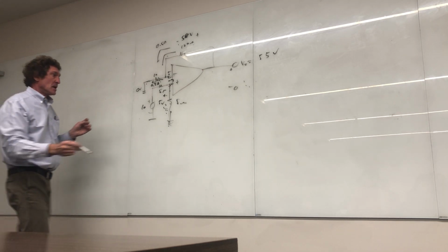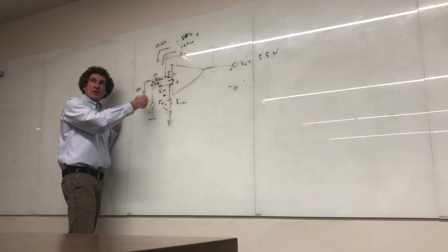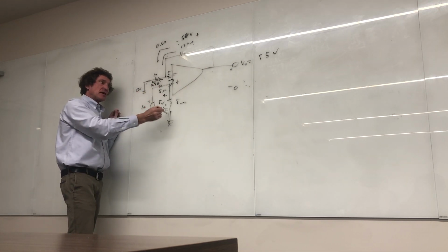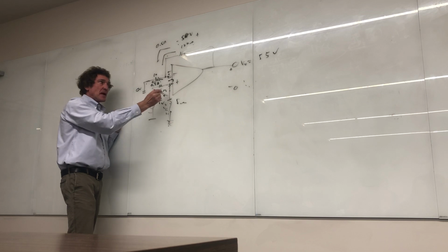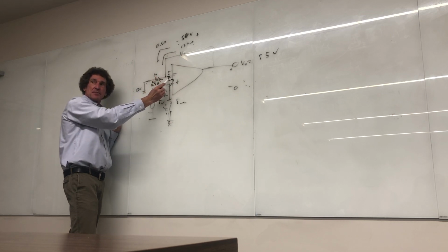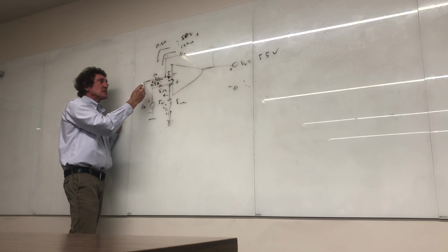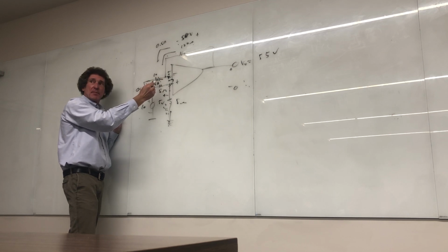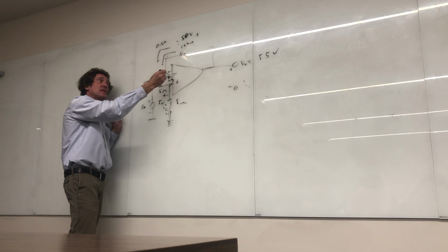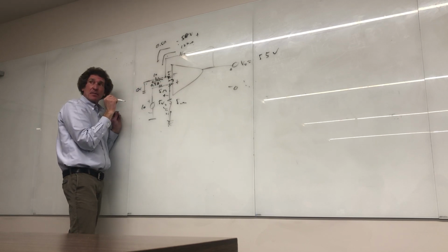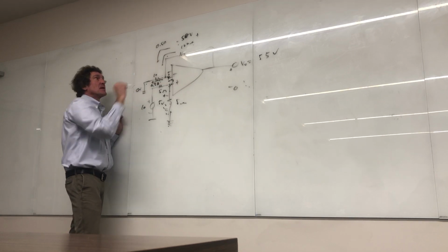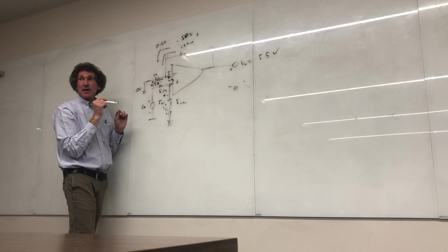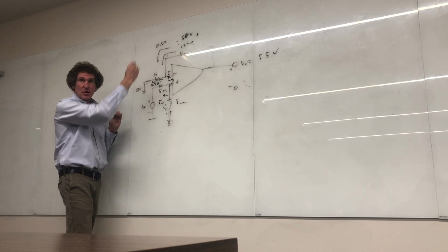Watch this carefully. Now this is a closed loop right here, right? First, you understand how I got 5 volts here. Now that 5 volts has to appear here, does it? Now 5 volts is here and there's 0 volts here. The current would be 5 over 10, or 1/2 amp, right? That current can't come from the negative terminal, it has to come from there, right? 1/2 amp times 100 ohms is 50 volts, right? Then the output, you just go through and you get it.